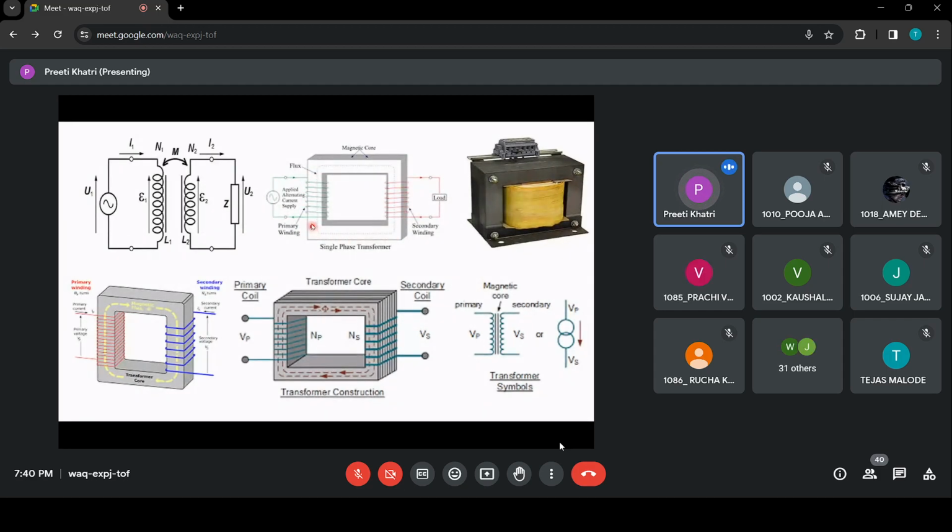So it is set up in the magnetic core there, most of which is linked with the coil which is present on the first side as well as the other coil which is present here. Thereby, according to Faraday's law, it induces the self-induced EMF in the first coil and the mutually induced EMF in the second coil there.